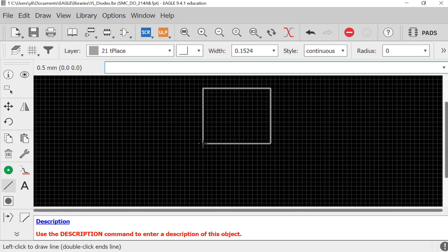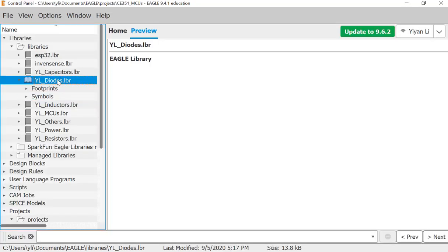All right, 6.5. And you need the two pads, and at the same time you need a bar to show the cathode and anode, to differentiate cathode and anode. So I'm going to directly do a bar not in the middle, but on one side. So this will be cathode, this will be anode. Normally they like to use pin 1 as anode, but we want to double check if that is true, so we are not connecting the pins to a wrong place.